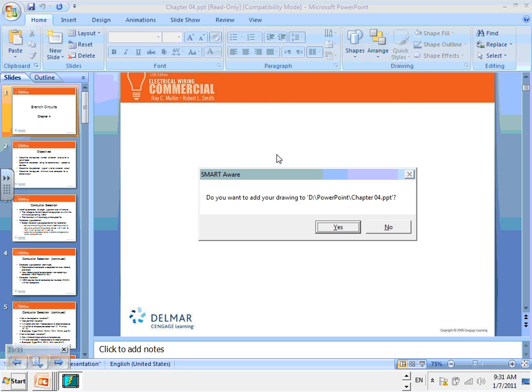And then the part I don't like, guys: the ambient temperature that we calculated, all this is at 30. What the author did is he mixed the derating with the continuous load, so derating and continuous load all in one. So now he thinks, okay, what if we need to derate? If the ambient temperature is 30, I don't need to derate. The correction factor is 1, because the temperature is 30, no derating based on temperature.